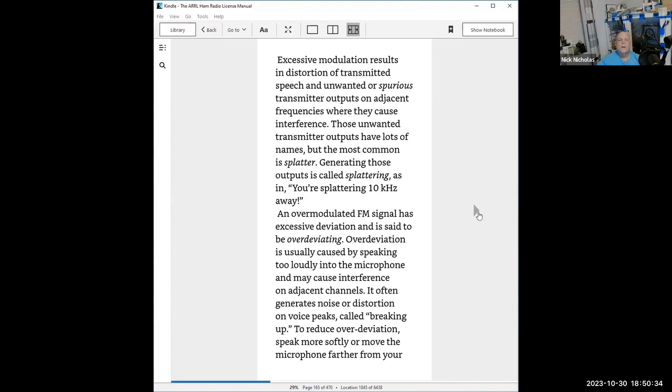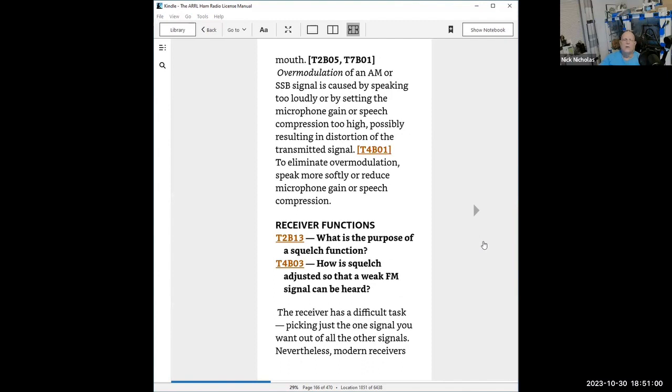I already told you that overmodulating an FM signal, or causing FM audio to be driven too hard, will cause you to over deviate. And excess deviation is over deviating. And I've told you why. It's just as simple as that. It's not much to cover. I already covered the AM signal, and why over driving causes over modulation. There's no deviation in AM, but it's over modulation, and why that holds true. Are there any questions about all of this?